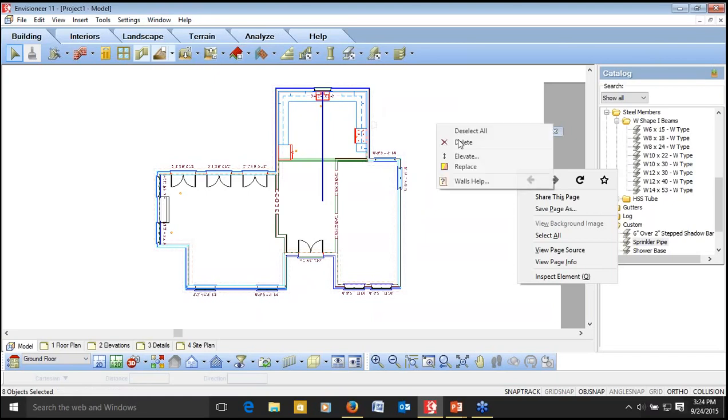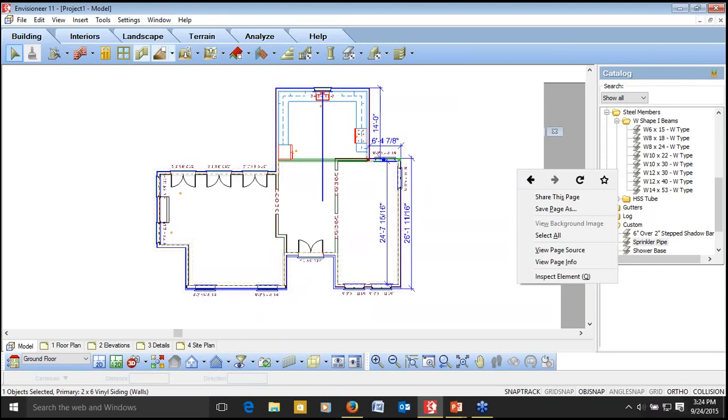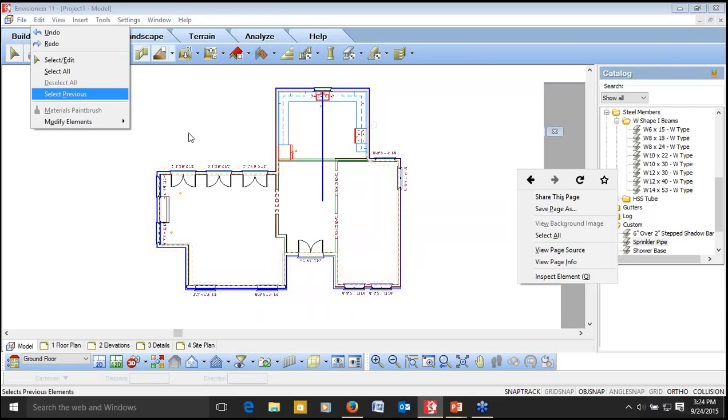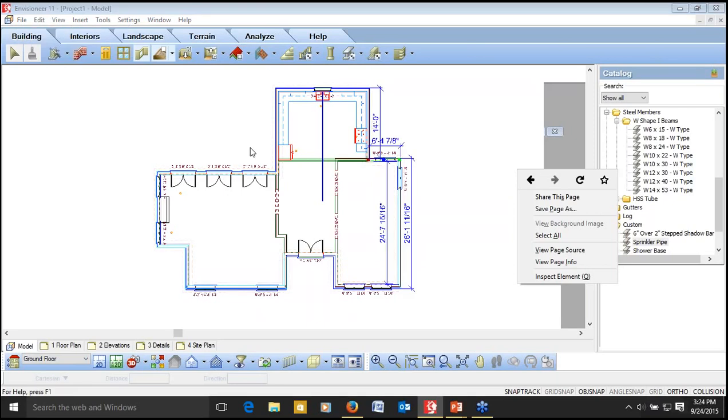For the walls that I selected, let me just select that again. Select all similar, but do not select you, you, and you. I'm going to look at the properties of those walls that I've selected. And when I'm looking at their properties, I want to tell them that with those walls, I don't want them to be a general wall.